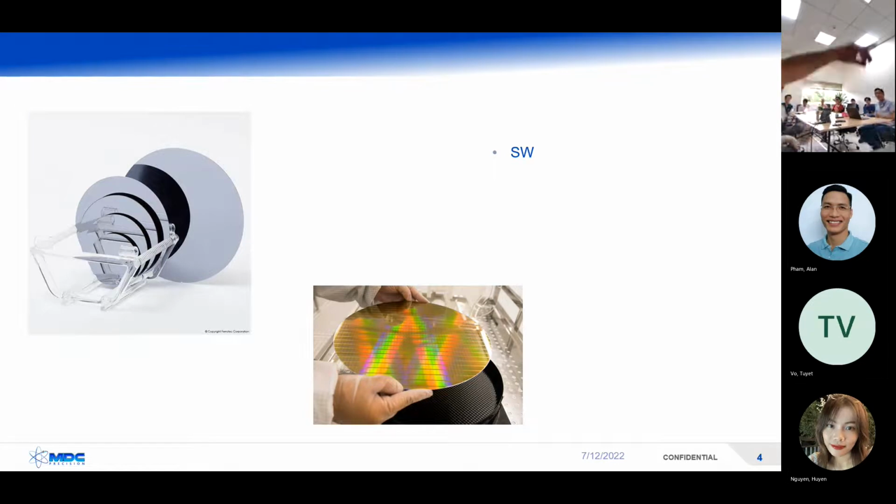Now, you hear us talk about wafers. We start with a silicon wafer that looks like the one over here. That's just a bare silicon wafer. Then when we build up those 100 layers, you can see on this one for people online, the little square areas. Those are each a semiconductor die. Most of the thickness is still the wafer itself. Afterwards, along those lines, called scribe lines, they cut the chips up and put them into individual packages.